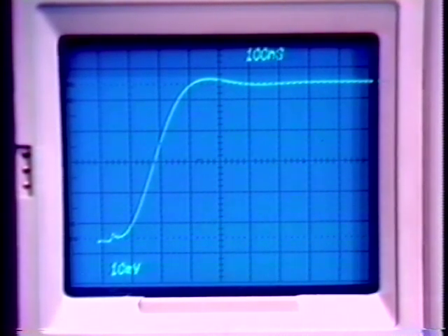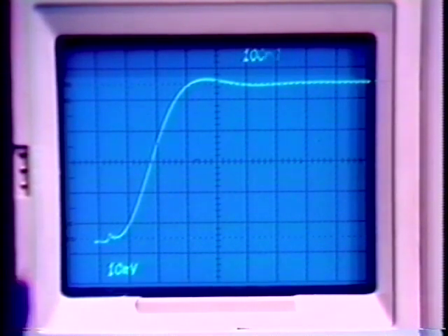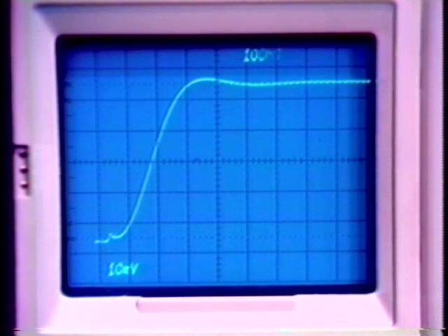If we wish to, we could slow the overall system. We can certainly use larger than 20 picofarad capacitors. That would result in somewhat improved stability, although the stability of this one certainly looks good for many applications, but would also generally slow the system. And in fact, the crossover of the major loop would drop just about in proportion to that capacitor size.